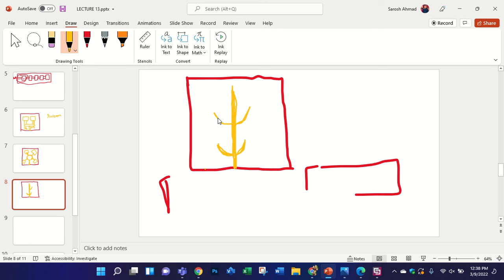And then you can again use here, like this, a tree shape technique, and they have connected the patch like this. In this way you can increase the number of elements, and you can get higher gain and efficiency. But it is more suggestible if you use the full ground plane behind the substrate. If you use a CPW technique here, you will not get much higher gain and will not get a directional radiation pattern. So it is better if you use the full ground plane, or partial ground plane, behind the substrate of the antenna.